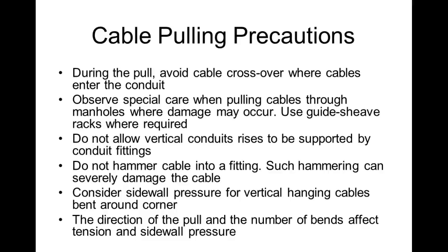I understand that. What does that mean? What does a rise mean? So this is a rise back here. When you put a fitting on the conduit, you don't want that fitting to support the rise, to support the conduit. So what do you do? Well, you use clamps, you use braces, and all kinds of stuff.